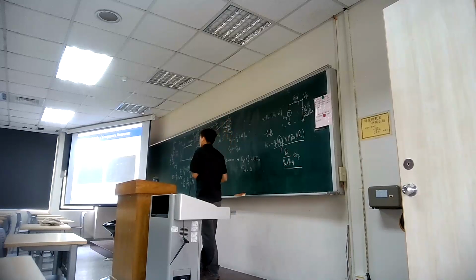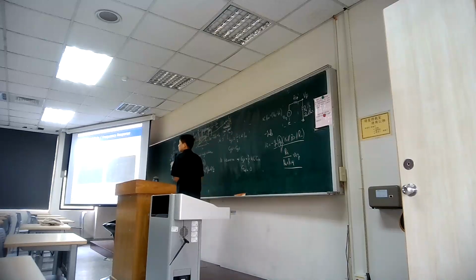What else can we do? Okay, so people work with low-k materials. The reason is because they want to boost up your frequency response. So maybe you heard about high-k, you heard about low-k. For high-k material, probably we use it as the gate material in which we want to boost up the current. For low-k material, we want to replace the surrounding insulator, or the conventional way we use oxide. But here we want to replace it with certain low-k material. What is the lowest k we can get?